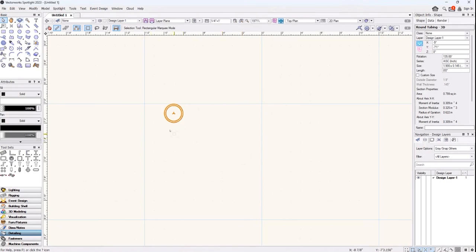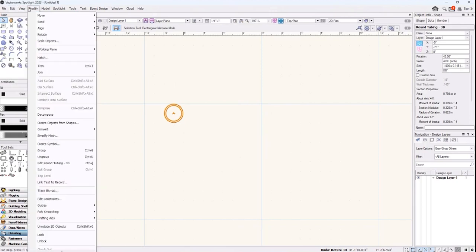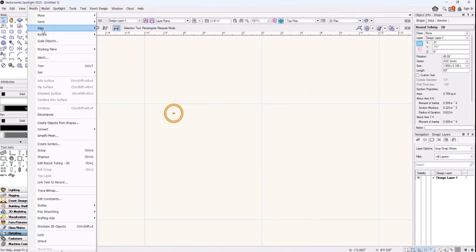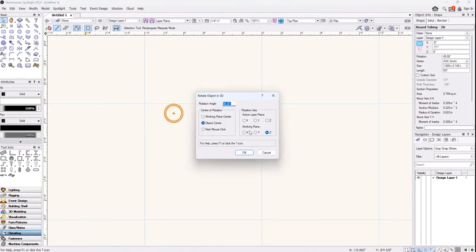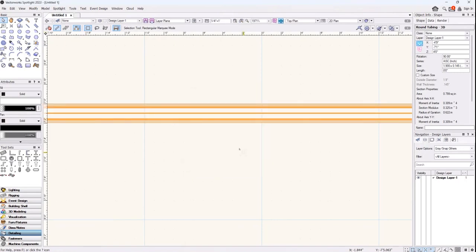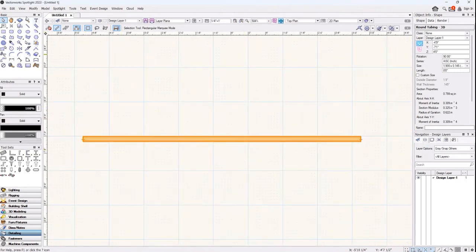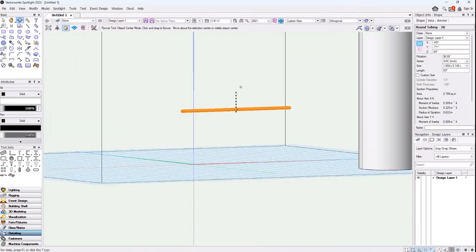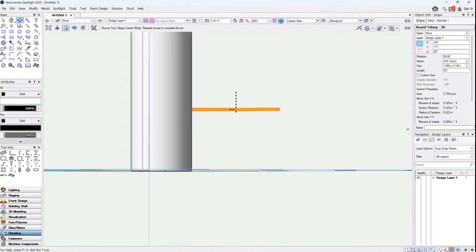and it didn't do anything. So we didn't pick the right plane. And to undo anything, it's always just Control Z or Edit Undo. Once again, we'll go back up to Modify, Rotate, Rotate 3D, and we'll pick the Y plane. And now as you see, it's rotated it horizontally. And now it could be something like a 5-point or something.